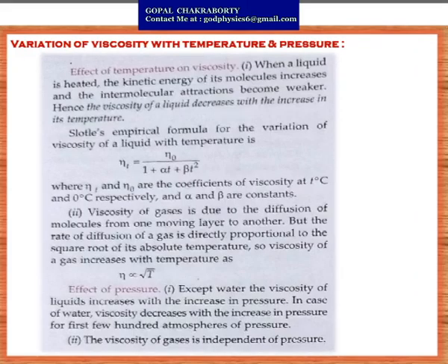Now this viscosity actually depends on the change in temperature and change in pressure. So how does it change? First, the effect of temperature on viscosity. When a liquid is heated, the kinetic energy of its molecules increases and the intermolecular attraction becomes weaker. Hence the viscosity of a liquid decreases with increase in temperature.